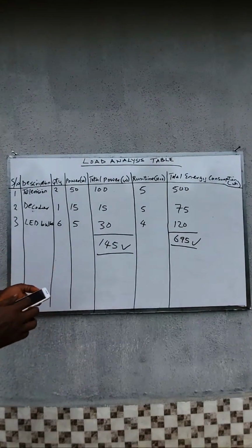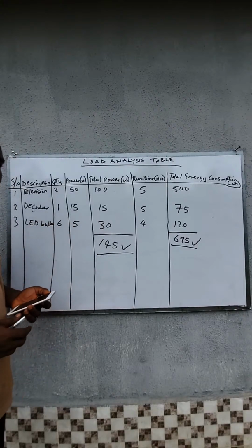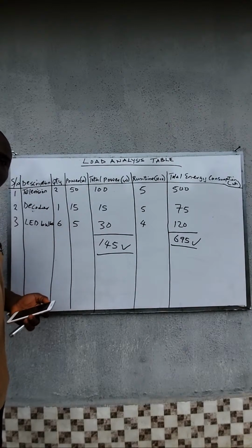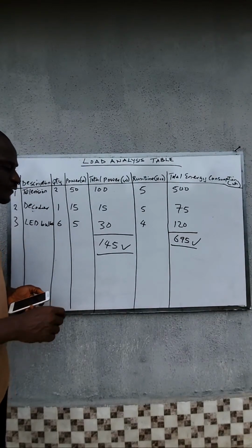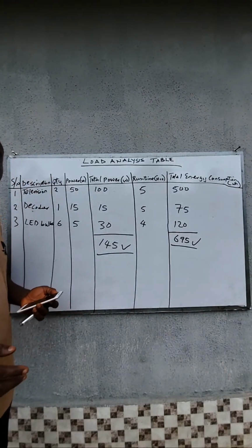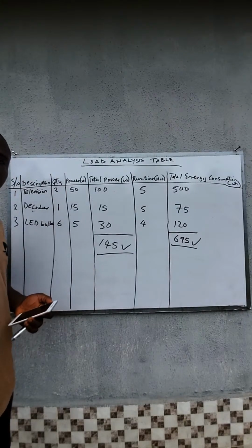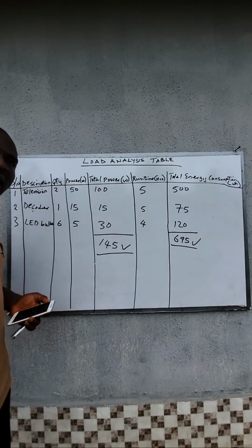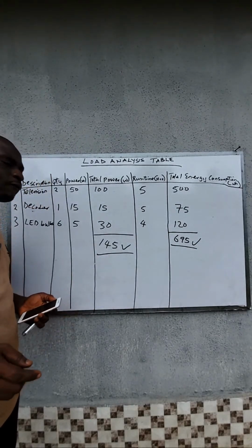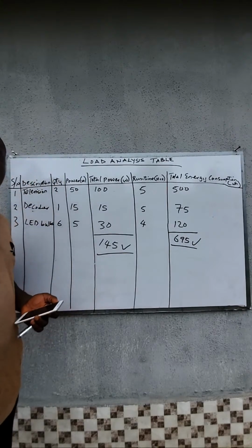Even when you're buying inverters, if you look at the specifications of these modern inverters, they will tell you the starting power of that inverter. The inverter may be rated at 3,000 watts, but the manufacturer will tell you that this inverter is capable of starting a 1 horsepower water pump or a load that is up to 6,000 watts.